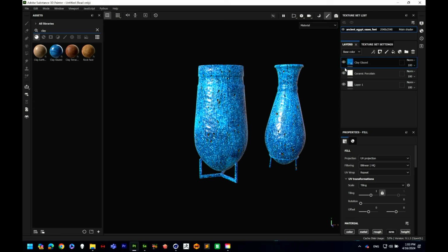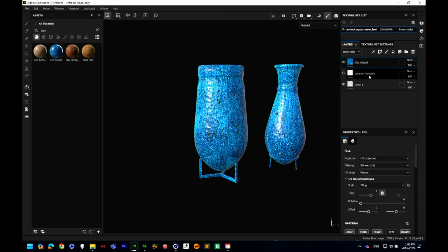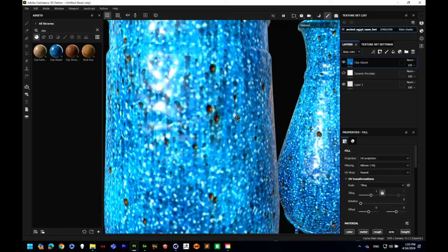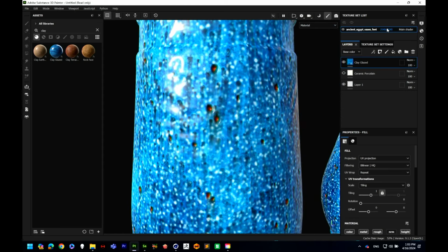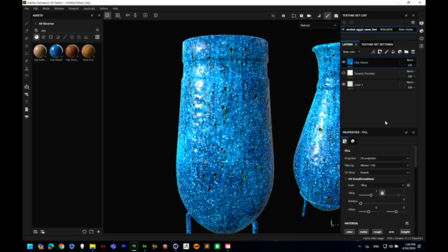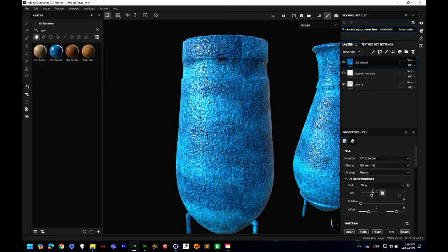And when you see over here on the right-hand side, I have those two materials applied onto my model. So I have the clay glaze and I have the porcelain. So let's just do the clay glaze because it's a little bit more visually interesting to see. The porcelain's more subtle. It's a very, very nice material, but it's not as visually interesting for the showfloor. But if we zoom in here, it looks pretty good. Obviously not as good as we can see. If we go up here though, we can change our texture resolution. So instead of 2K, we can move up to 4K to get much better material quality out of this clay glaze material. And if we increase the tiling as well, we should be able to see it a little bit better visually applied onto my object.